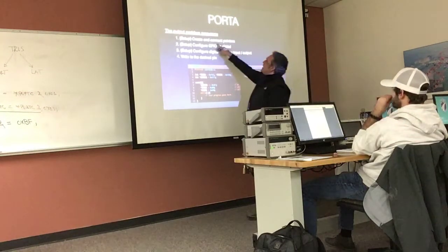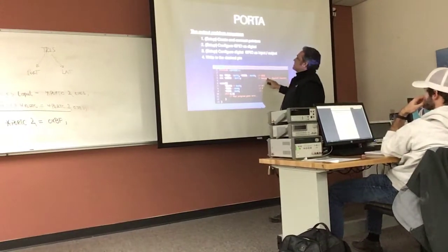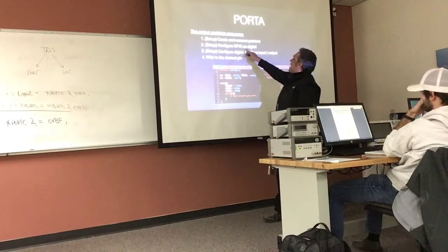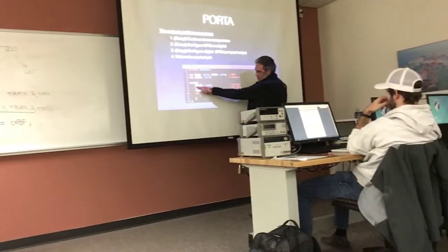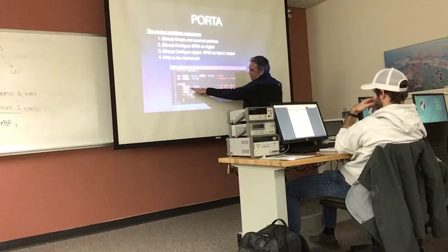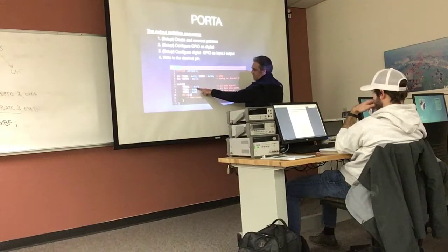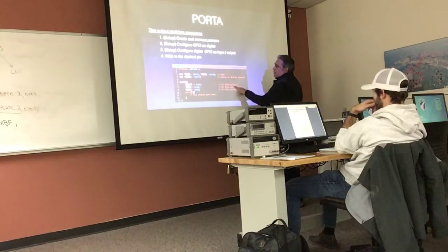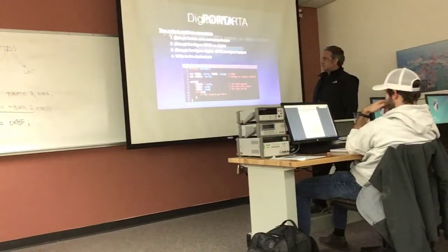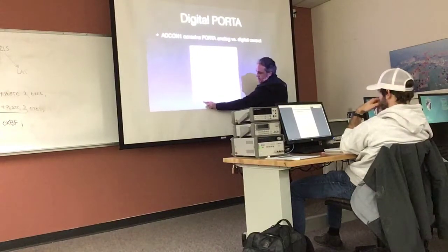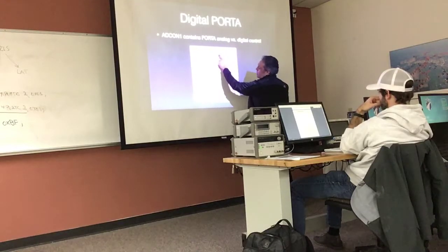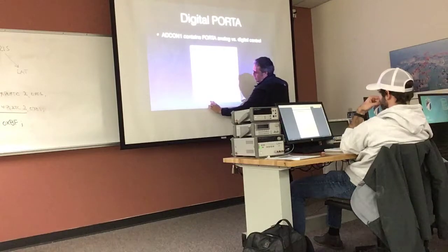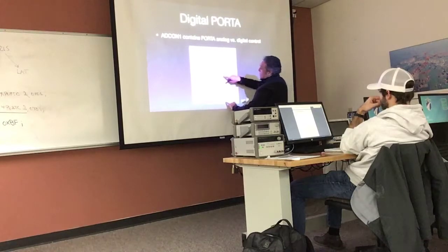So here we go. Step 1. Create and connect your pointers. So that's here. Step 2. Configure the GPIO as digital. And this is for port A because port A could be analog or digital. And that's done right here. ADCON1 OR-gated with a hexadecimal F. That will make all GPIO pins digital. Let's look at it again. Look. If I put an F in these pins, I got 1, 1, 1, 1. That means that every single pin in the microprocessor goes to digital, including the 5 guys in A.